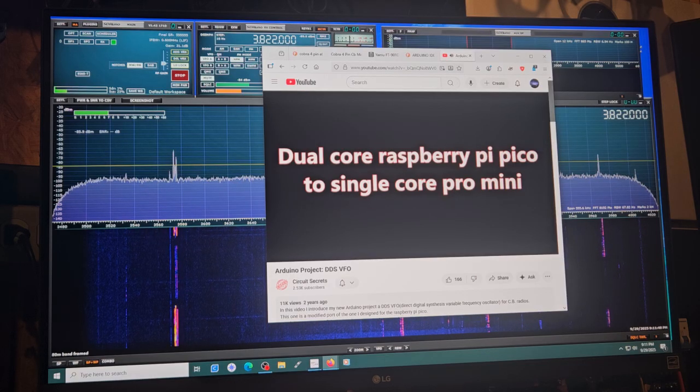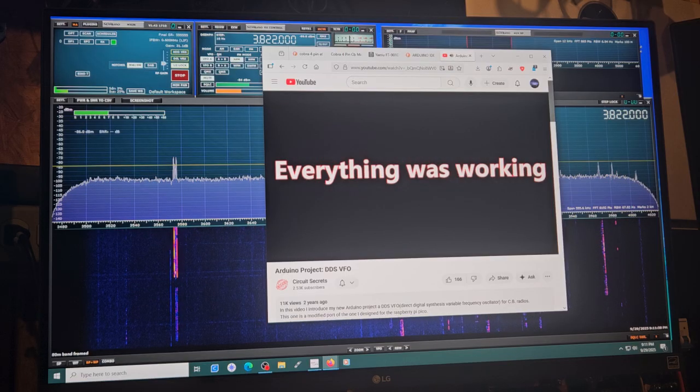I moved all of the setup 1 code into setup, and I moved all of the loop 1 code into loop. Then I set both devices to use wire, removing a device from wire 1. After these changes, it seemed to run fine. The display worked, and the SI5351 output the appropriate frequency. But there were still a lot of changes to be made.